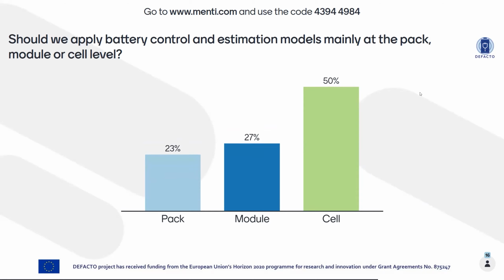Specifically, the number of current sensors and the location of the current sensors is very important, because that is the thing that underpins state of charge estimation. So my view on this is you should definitely have one state of charge estimator for each current sensor. So if you have multiple parallel strings, then it would make sense to perhaps run multiple Coulomb counters because you have different current sensors.